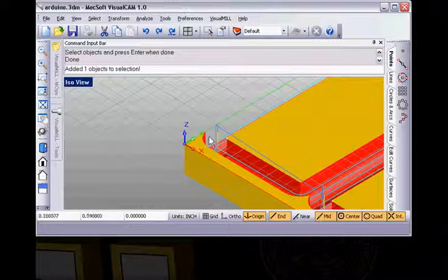So when this is cutting along the outside edge, it's actually cutting outside the stock, so there's not going to be any waste material over here. This is fine as long as I didn't put screws along this edge or some clamping mechanism. If I put a clamping block or a stop block over here, probably the likelihood is the cutter would have hit it.